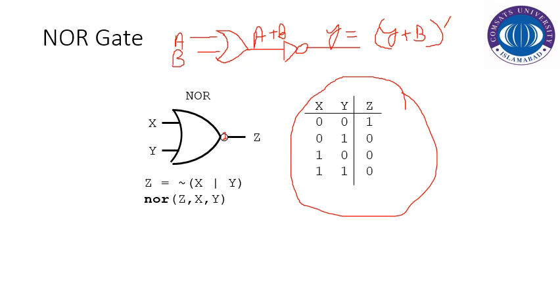This bubble, or circle, basically represents the inversion operation. So in any digital circuit, if you see any circle in front of the symbolic representation of any digital component, that basically represents the NOT operation, and that is the hollow bubble. If the bubble is filled, for example, where we have cross wires here and we are using this fill, this is not the inversion. Basically this represents the junction or the connection between the two wires here. So there is a difference between this circular representation with digital components and this junction or node to interconnect two elements here.